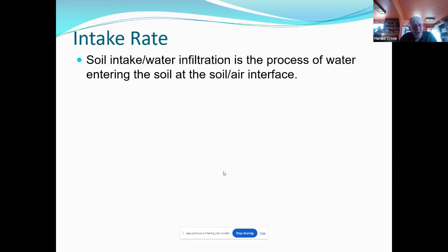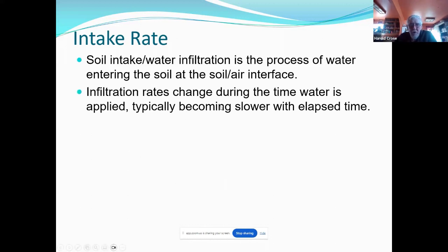There will be a point on this soil, at the slowest speed you can move this system, where you could actually get runoff from a soil like Warden silt loam, especially if there's an end gun. You're putting water on so slowly that it doesn't have a chance to infiltrate into the soil. It just can't take water in that fast. This is where you'll see runoff through the wheel tracks that are left in the field, and also through the bottom of the field, where we can actually pick up significant erosion from those events. So knowing how many inches can be applied, the infiltration rate is critical.